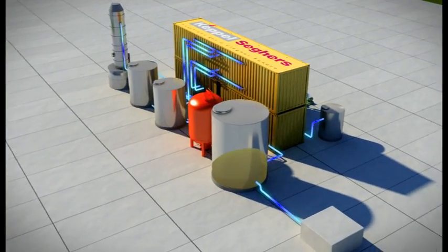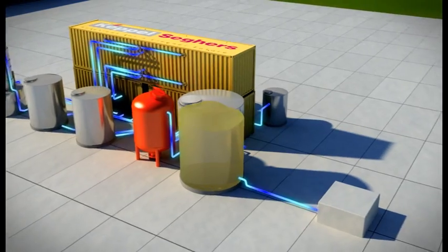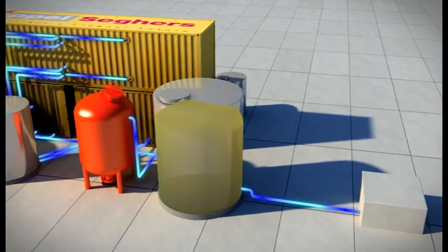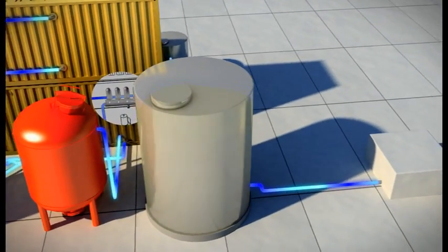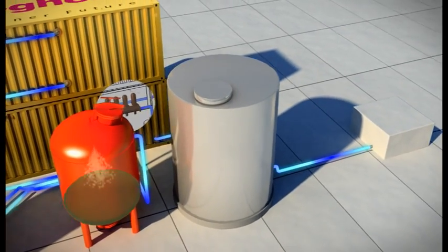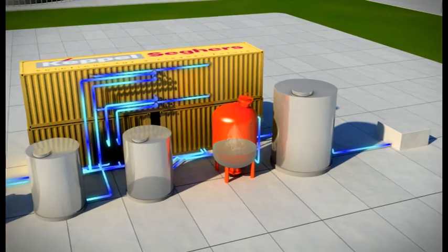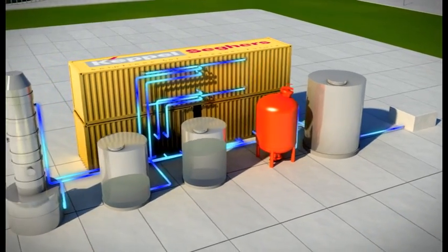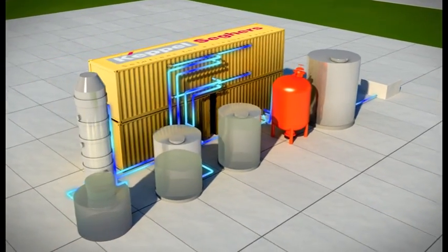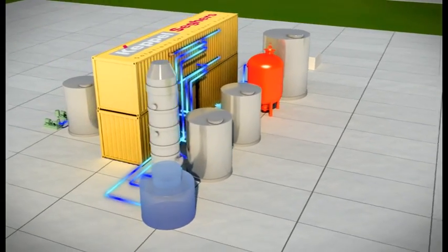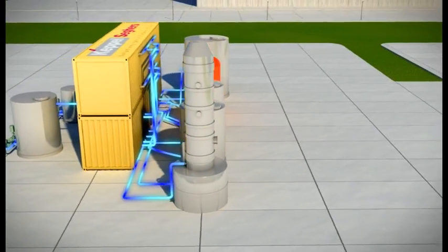Raw seawater is drawn from existing seawater bodies. The raw seawater is first passed through a particulate filter stage comprising auto strainers and granular media filters. This is to remove suspended solids and foreign matter. The raw seawater is next purified with a vacuum spray degasser, removing part of the dissolved gases.